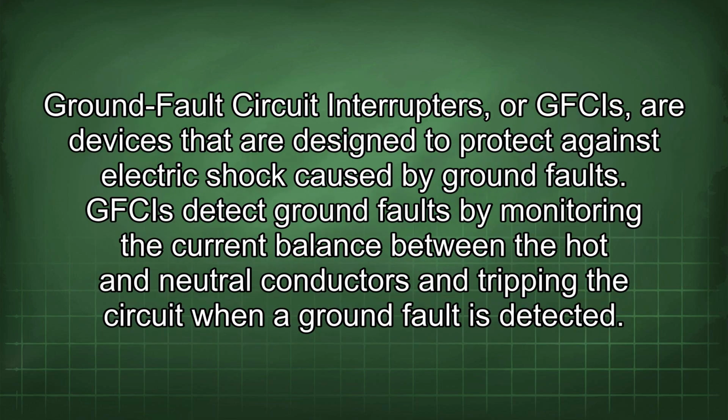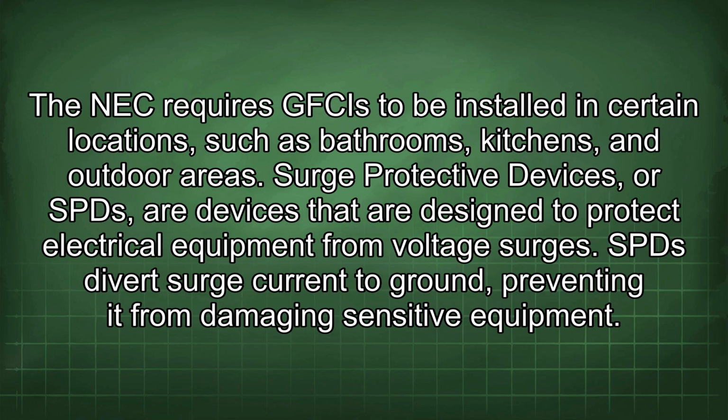Ground fault circuit interrupters, or GFCIs, are devices that are designed to protect against electric shock caused by ground faults. GFCIs detect ground faults by monitoring the current balance between the hot and neutral conductors and tripping the circuit when a ground fault is detected. The NEC requires GFCIs to be installed in certain locations, such as bathrooms, kitchens, and outdoor areas.